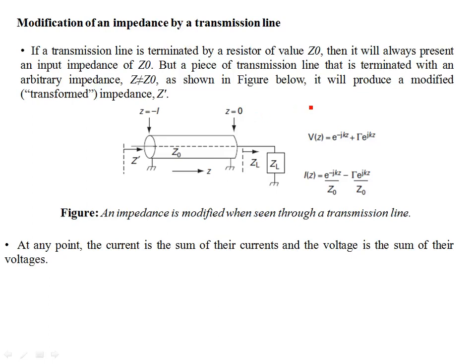If you recall from our previous discussions, if a transmission line is terminated into its characteristic impedance, for example, if you have a transmission line, let's say a parallel two-conductor wire, which is propagating the electromagnetic energy, it could be a transverse electromagnetic (TEM) wave mode of propagation, and it's terminated into a load which is equal to its characteristic impedance, then there is no reflection.